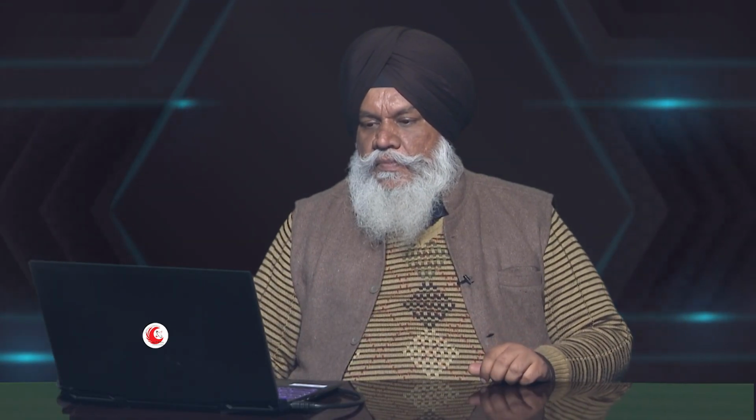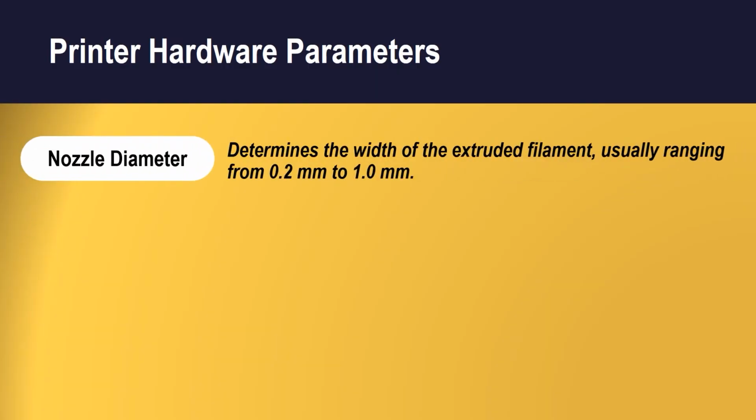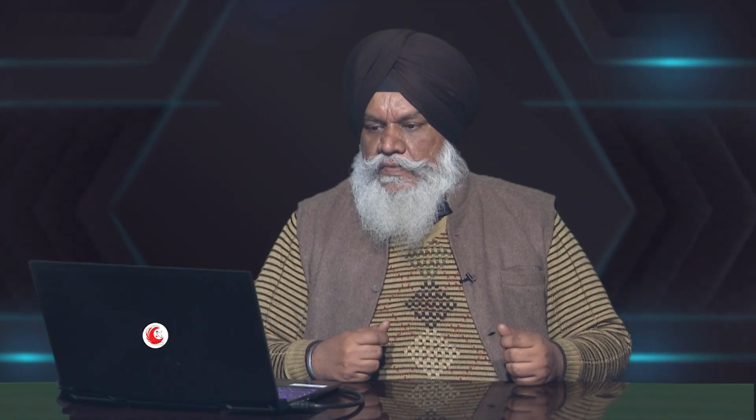Now in this discussion we will talk about some hardware parameters and some software parameters to run my printer more efficiently. So commercially, the nozzle diameter is something which is basically determining the width of the extruded filament, right? It varies from 0.2 to 1 mm. For example, if you want to make a thin section, I have to keep it to the minimum size, and if I want to make a thick section, I can use a larger diameter of the nozzle.